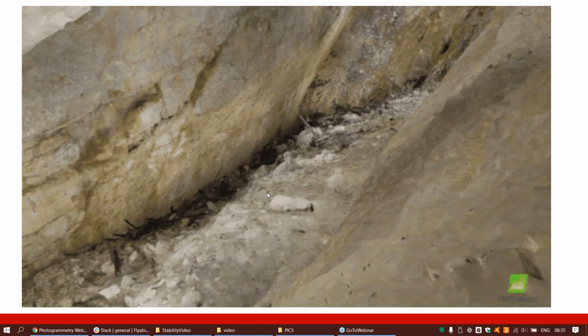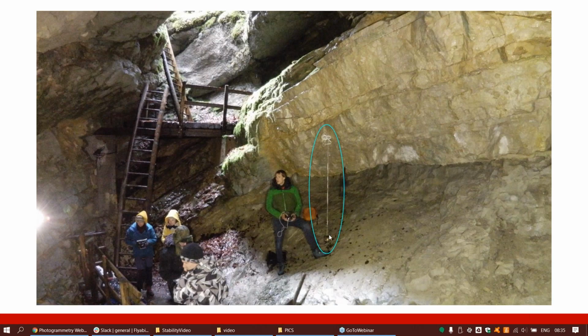As a scale reference, we again use this bob weight, so that gives you a scale. It also gives you a z-axis, which you also need to manually insert. There's two black stripes there, which are poorly visible. What we learned from this is you're better off putting retroreflective material stickers on those instead of making black stripes, because you can see those from much further away. So one of the conclusions from this is that I always carry a fishing line with a bunch of these reflective stickers on every meter, so I can just hang it up wherever I need it.